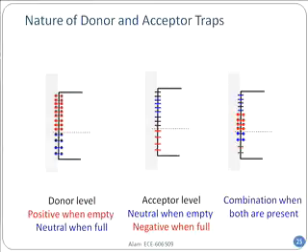Now, many times these levels, depending on how the hydrogen bonds are oriented in different directions, may behave either like a donor level or an acceptor level. So in general, what I have shown on the right-hand side is that you will have a combination. Do you realize the dumbbell shaped blue ones, these will be positively charged, right? I'm sorry, those would be neutral, because they are below the Fermi level and donor-like. And the dumbbell shaped red ones will be positive. And similarly, what will happen to the short red segments on the right?